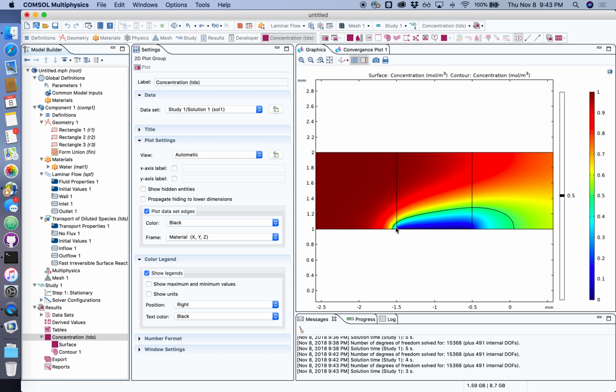And interestingly, right here you can see that the depletion zone is actually growing upstream. So this is showing us that we are finally reaching a slow enough flow. The convection, the flow from left to right here, is getting slow enough that it's still winning relative to diffusion, but some lucky solute molecules are actually able to diffuse to the right so fast that they diffuse faster than they are flowing. And in that case, that means that they are sort of locally depleting the region upstream of our sensor. Just this little bit here, they're depleting it of our target molecules and causing a depletion shape that's actually starting to work its way upstream, interestingly.